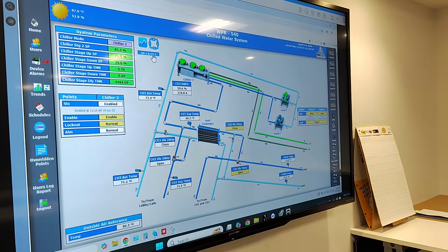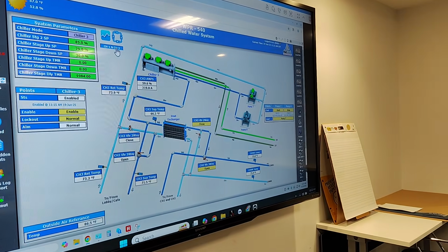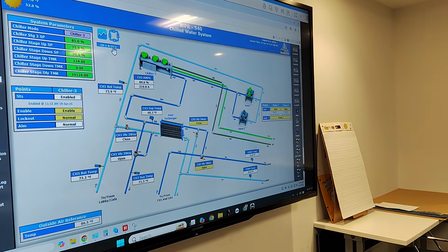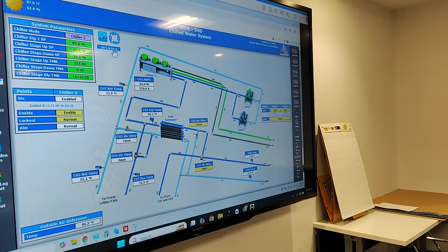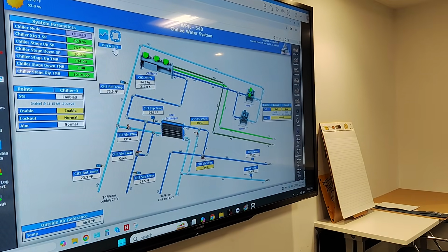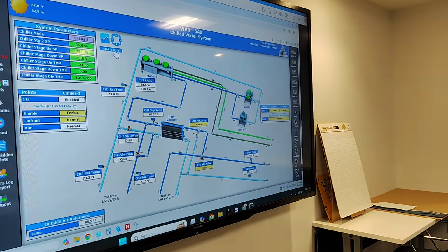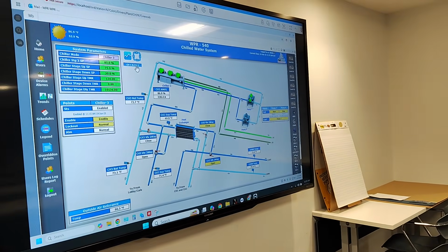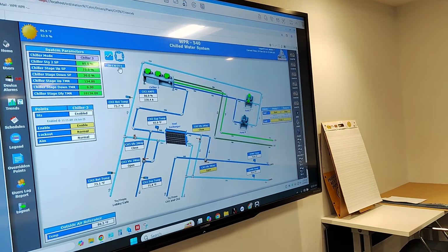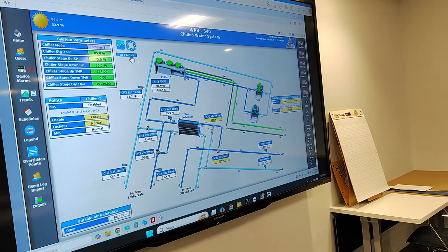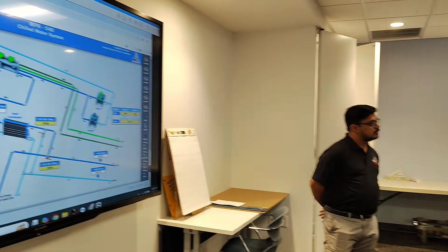It's like a big diagram, that's why we put it into two sections. The temperature looks like it dropped a little bit. It was 74 before, right? Yeah, but it went to 66. So it's coming down, but it's still way too hot for chilled water. I know, but it wasn't on. That was the issue. It cycled off for some reason. It is coming down, so we'll see if it gets to 44. If it gets to 44, you'll at least get cooling in the building.